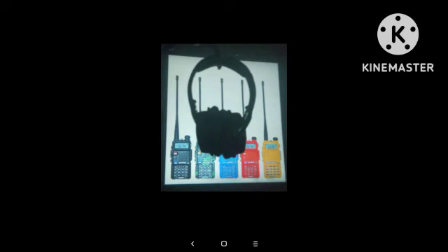Number 58. Two mobile stations are traveling along the same road in close proximity to each other and having trouble communicating through a local repeater. Why may it be necessary to use simplex operations to communicate between these cars? The strong signal of one mobile may desensitize the receiver of the other mobile.